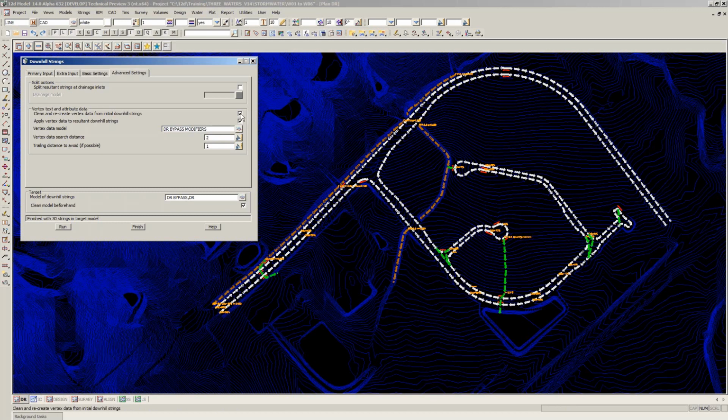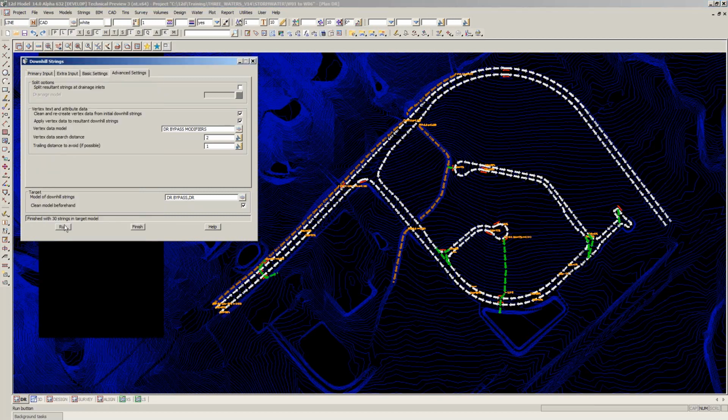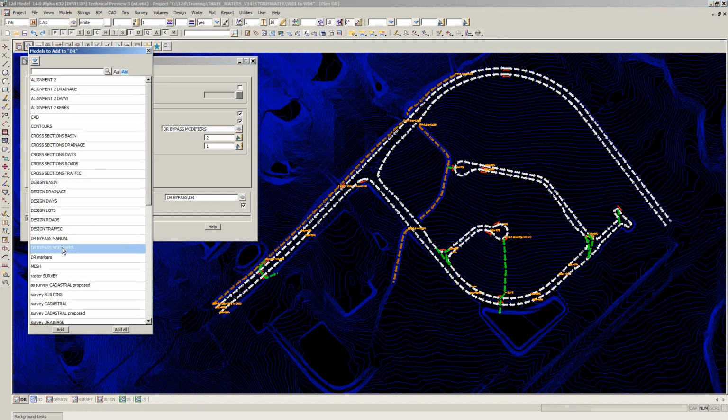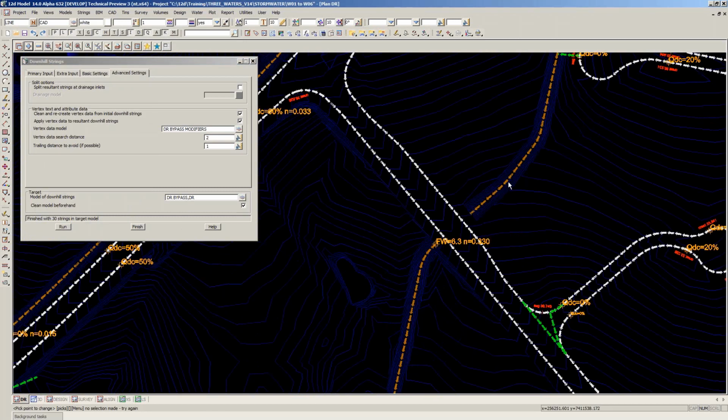Look, once you've got the data in both, or even from the word go, the way I demonstrated it was just for demonstration purposes. You can have both tick boxes on, and if the data is on the original bypass model, as it is here, I can simply rerun that and everything's fine, and you can just never even bother looking in this model. But it's there as a safety mechanism, basically. It also means that you can modify, using the utility string editor, the stuff in this model and have it independent of the vertex attributes on the bypass strings. In fact, if you have one of these modifiers, you can see the modifiers have the little crosshair symbol on them, and you can move them around. They don't have to be on one of the vertices of the string.